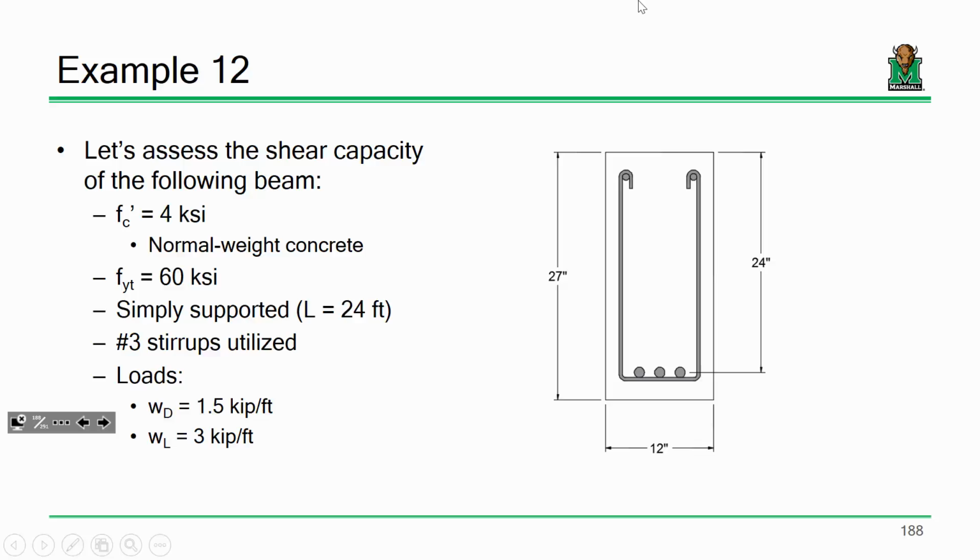It makes more sense to do it gradually instead of these are 4 inches and these are 8. Yes, we do try and do discrete sort of lumps of stirrup spacing. So we might have so many at 4 inches and then so many at 8 inches and then so many at 12 inches.